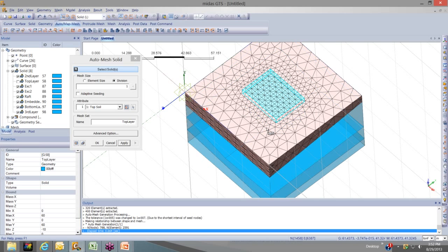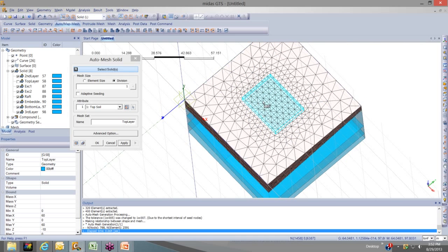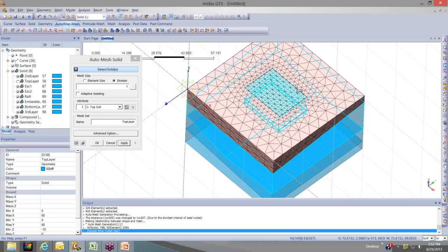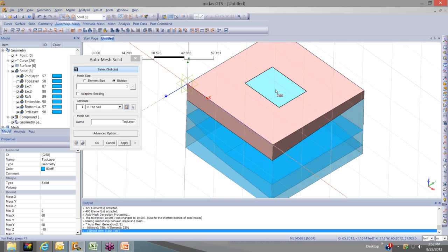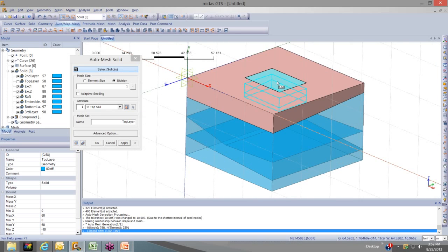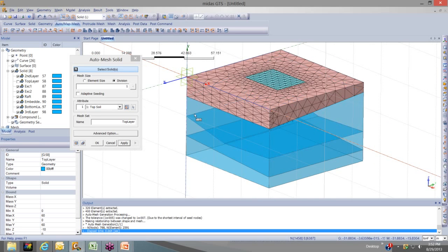And that was the whole purpose behind doing the mesh seeds, so that the program would recognize, I set this to 10 and this equally to 10. So the program would recognize that as I get closer to this point, the mesh would become finer. That was the whole purpose behind doing the mesh seeding at the beginning. Okay, so now let's just finish up the rest of these mesh sets here.